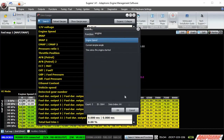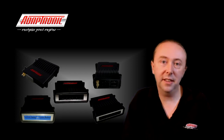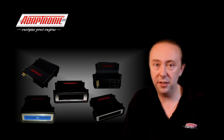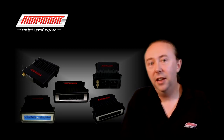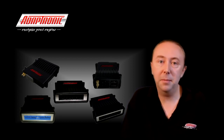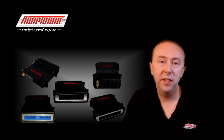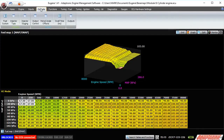I'll start first with pre-programmed logical outputs. These are outputs whose functions are designed into the ECU, and they're normally things that are either 0 or 100% duty cycle. Examples of this would be, say, thermofan stage 1, fuel pump, check light on off, and that sort of thing. There are some other pre-programmed outputs which have a variable duty cycle, which can vary between 0 to 100%. So this would include the idle effort, variable valve timing, pulse width modulated duty cycle, boost control, and so on. Let's have a look at the output screen in Eugene.